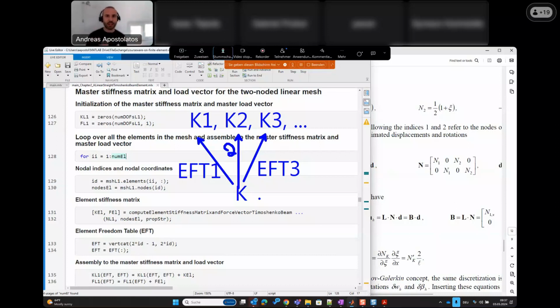But in the finite element analysis 1, where you had truss systems, as Isaac said, you first transformed from the local coordinate system to the global coordinate system, and afterwards used the element freedom tables to construct the master stiffness matrix. So you had 2 steps. What I'm teaching here in the frame of this course, you don't need to do any coordinate transformation. It's just straight computing the stiffness matrix at the element level, and then using the element freedom table, you put it directly on the stiffness matrix. So there is no coordinate transformation here. Hopefully that makes sense.